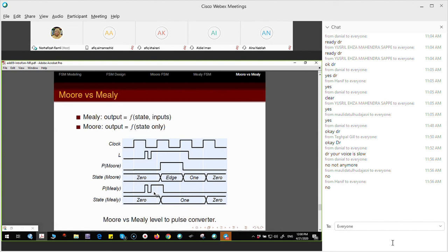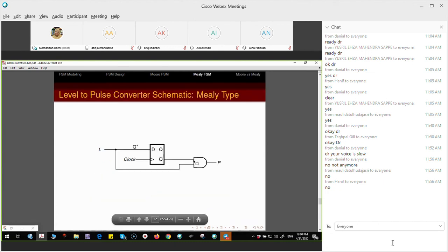If you register the output, meaning the output will stay, for example, this first output will stay at 1 for the whole clock time. So that means you don't see this jittering. If you do not register the output, then what happens is that when you register, right after this comes out, there is another register just to hold the data. If you have the data held, then you don't have that flickering here.